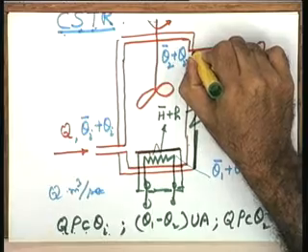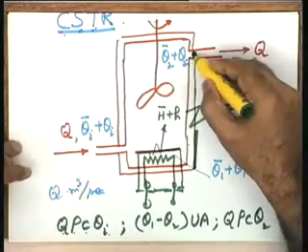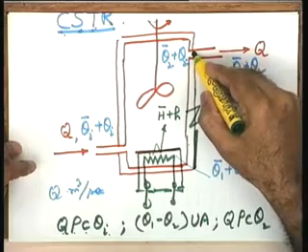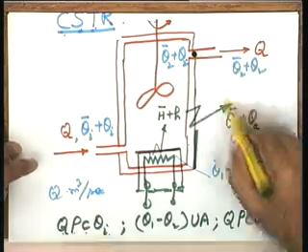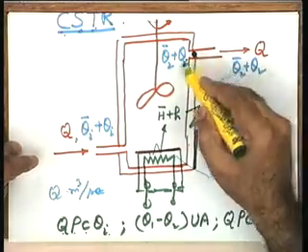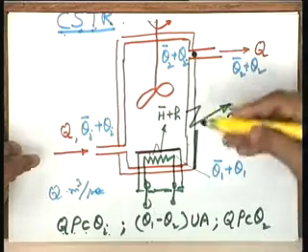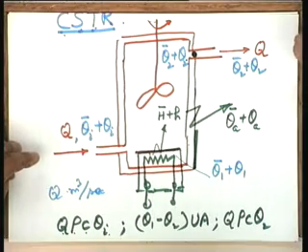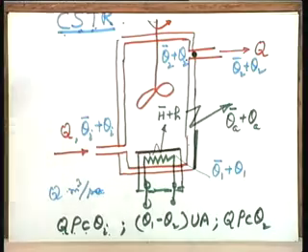Note my point please. And therefore, if a sensor is placed over here, in addition to the useful information, that is a voltage proportional to the controlled temperature, the noise signal will also be going in the feedback loop, through the feedback loop into the plant, and the noise may even dominate the useful signal, and therefore the control action will not be the way you want it to happen. So, what are the